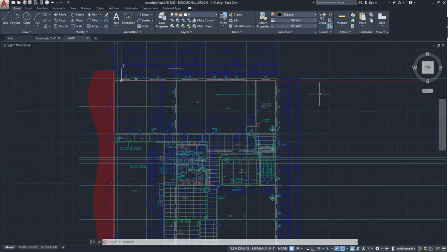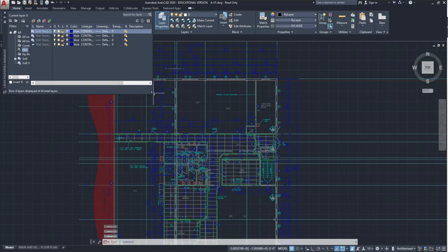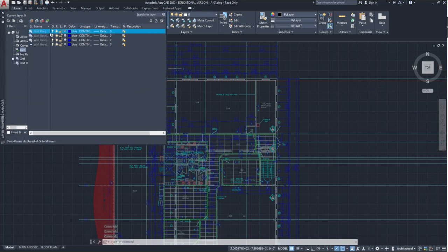So in addition to allowing lines to have a line weight in AutoCAD, layers will allow you to organize lines in AutoCAD, okay? And lines are organized according to architectural element. So what that means is, hopefully their layers are correct in here. You're going to create layers according to architectural element, okay, or whatever you're doing, right? Whether you're an engineer or an architect or whatever, you're going to group your layers and your lines onto those layers according to element. So for example, all the doors are going to be on one layer, okay? All the walls will be on another layer. All of the plumbing fixtures will be on another layer, right? You guys get the idea.